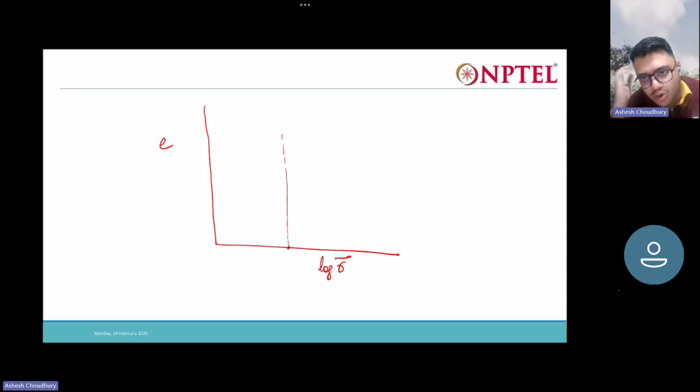Before, you had loaded it to this stress level, so our soil will be called over consolidated. Now as you increase the load from zero, our curve will be like this, because up to this point our soil is over consolidated. And this is my initial void ratio.